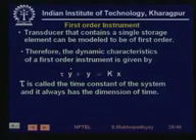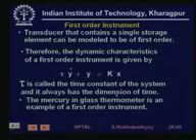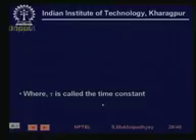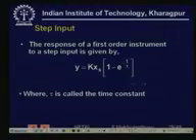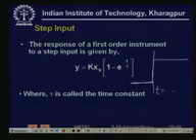So we can easily compute the response of a sensor whose input is a step input. Let us try to characterize the response of this kind of sensor to various kinds of changing inputs. These are two examples: a mercury-in-glass thermometer and a thermocouple in a thermowell. The first kind of input that we consider is a step input. Step input means it is at 0 and then suddenly it rises. So at t equal to 0, the input is 1, suppose.